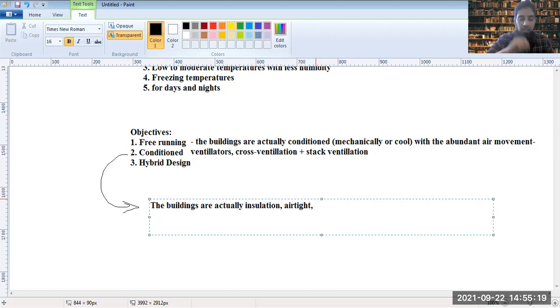Now, if there is a congestion in certain places, that you check, and for those areas which may have air sealing problems, these oxygen problems, there you provide ventilators, mechanical ventilators, which you switch on the exhaust for a certain period of time and you get an air movement through your house from the outside.